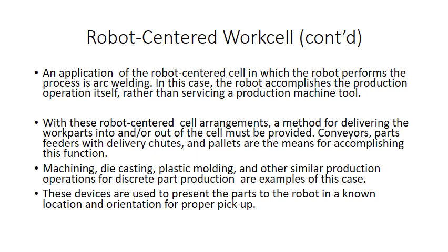With these robo-centered cell arrangements, a method for delivering the work parts into and or out of the cell must be provided. Conveyors, parts feeders with delivery chutes and pallets are the means for accomplishing this function.